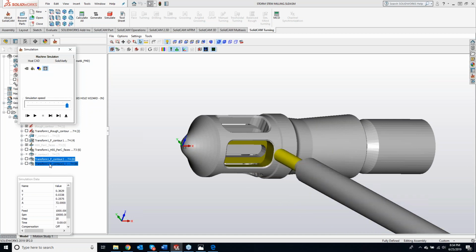See it now, it just jumped down to my contour 2-2. So it's basically doing a spring pass. What the customer wanted in this scenario is to do all the windows first and then come back and do the spring pass, because the burr, as he was machining out this window, was getting rolled over.